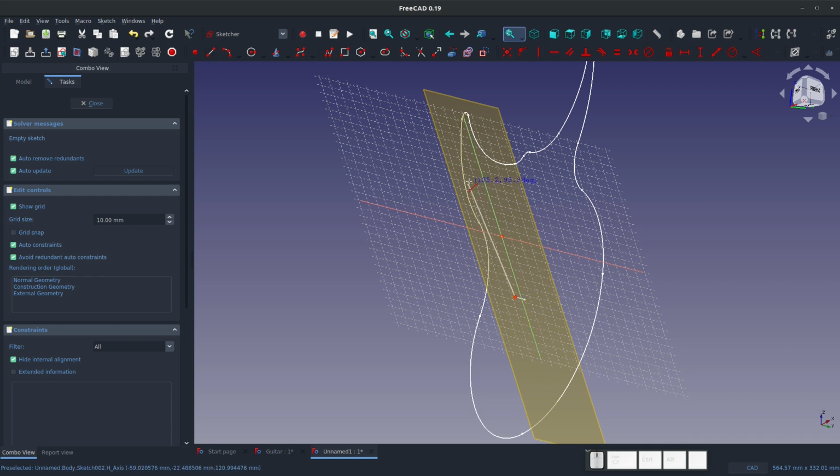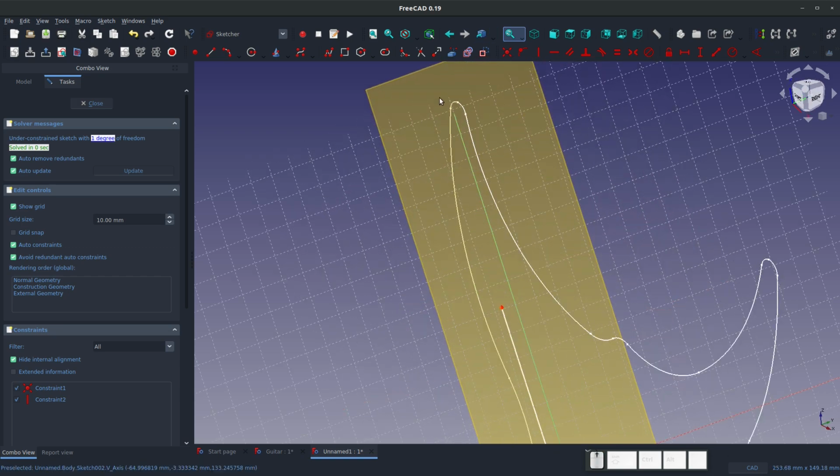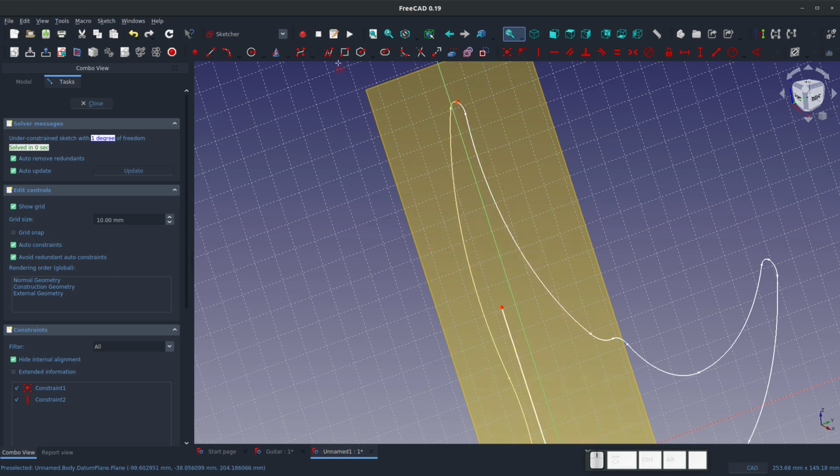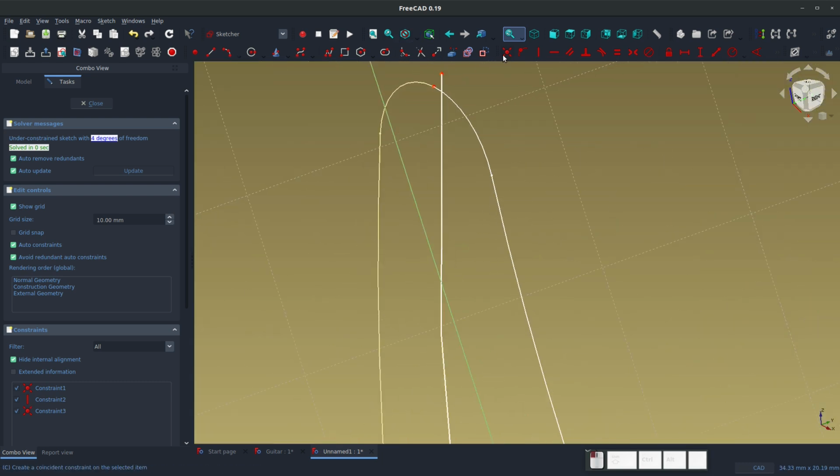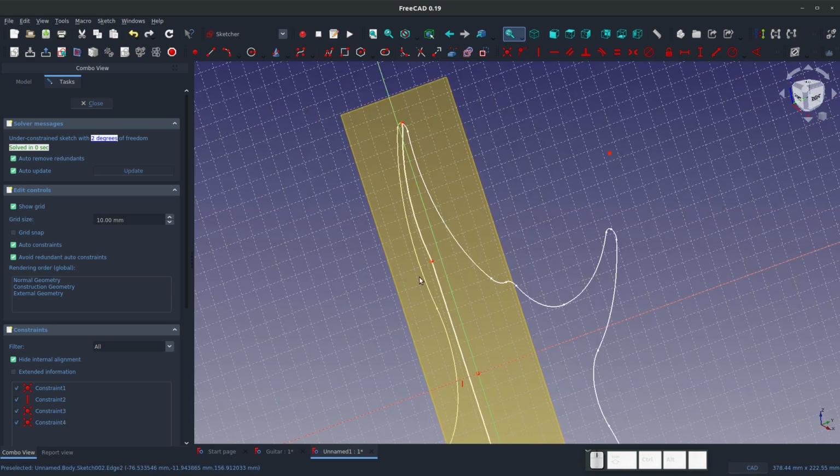And I'm going to go straight for a while. Looks like we have a nice vertical constraint added to that. And let's import the center point that we've referenced before. And I'm going to create an arc. It looks like we didn't snap onto that, so let's add a coincident constraint rather there.